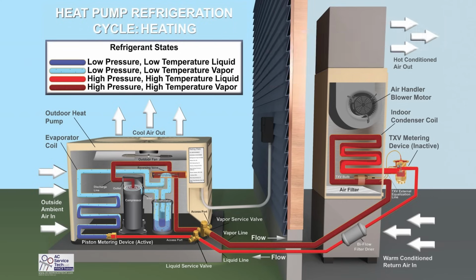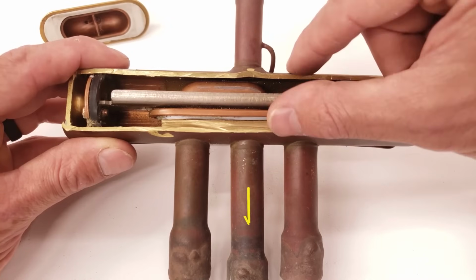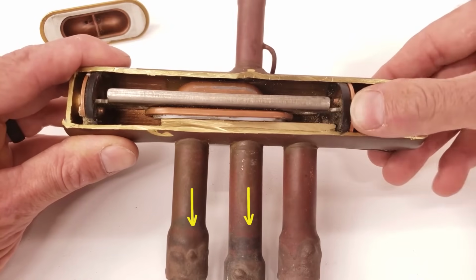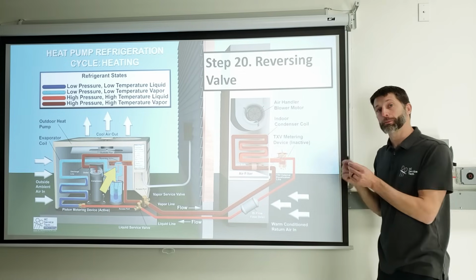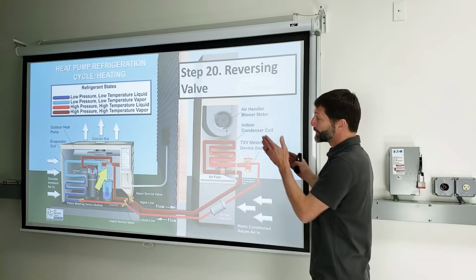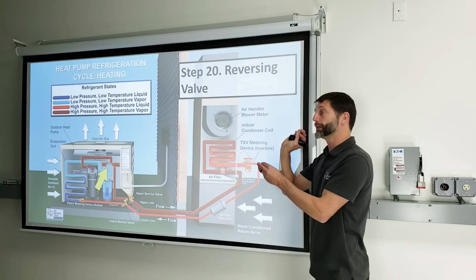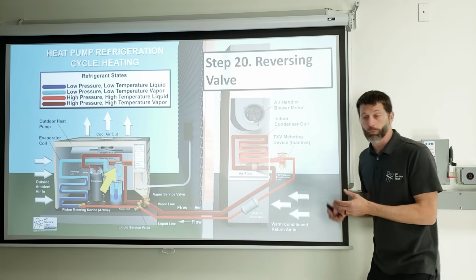And by the way, if you're ever wondering if that reversing valve is partially stuck, you can take a temperature measurement across 2 of those 4 tubes. The tubes that you're going to measure are the center of the 3 and the other low pressure, low temperature line. You're not going to measure the high temperature lines. For one thing, they're so hot that you could potentially damage your K-type temp sensor or whatever you're using. The other thing is the lower temperature lines are closer to the air temperature outside, so there's going to be less chance of errors when you're taking your measurements.